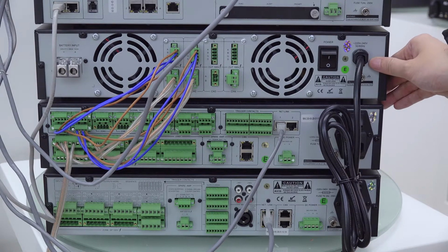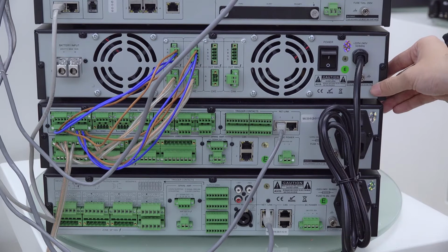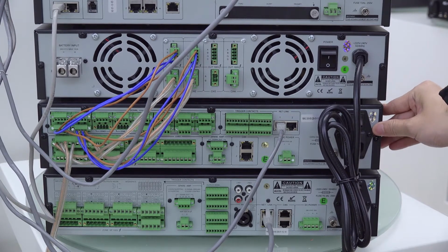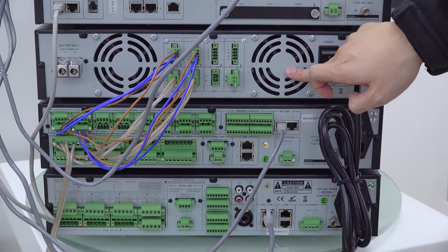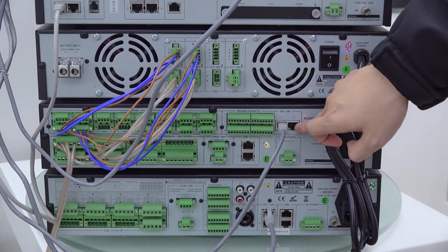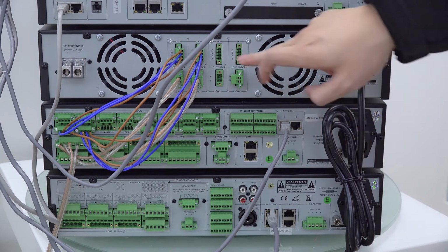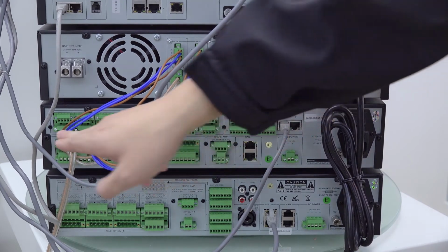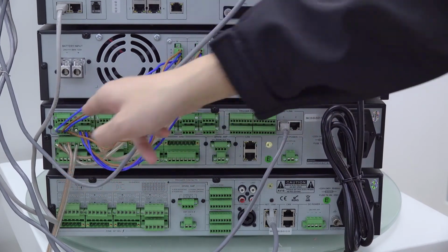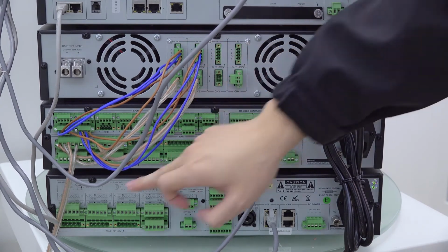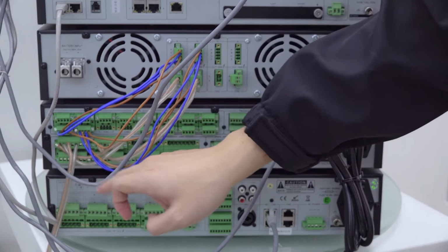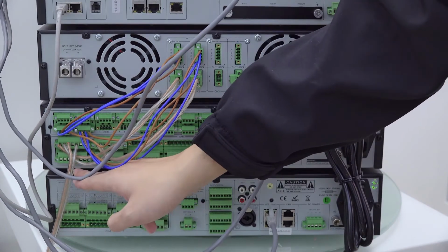After the evacuation controller, now we come to the signal partition parts. You can see there are 2 devices. This one is the 4-channel amplifier, and this one is our changeover. The 4-channel amplifier gets the audio signal from the changeover first. Then it will output the signal to the changeover. After that, the changeover will output the signal to the speaker directly.